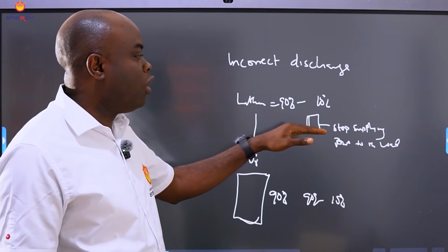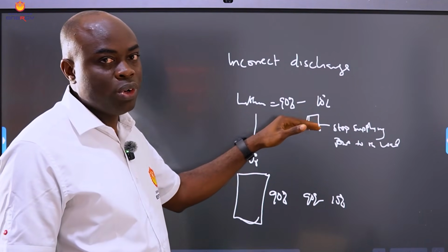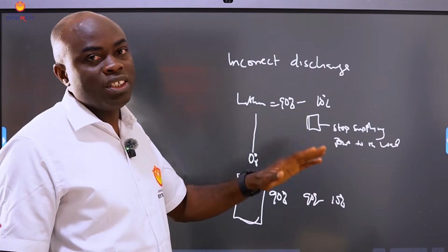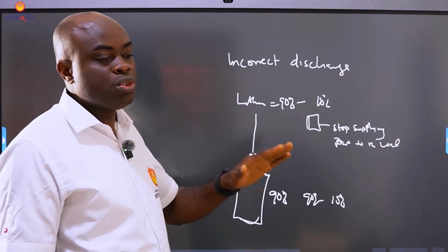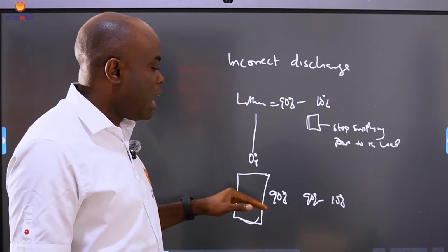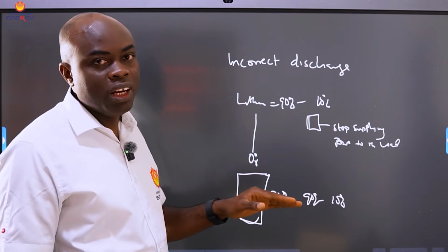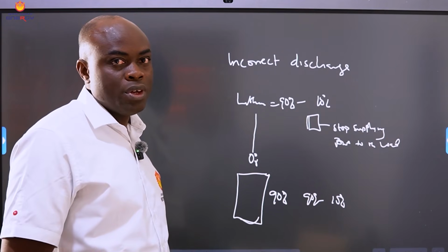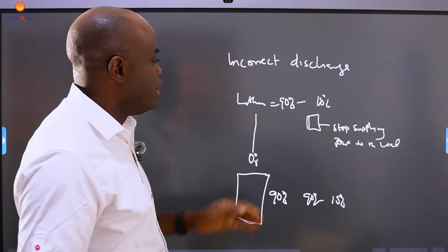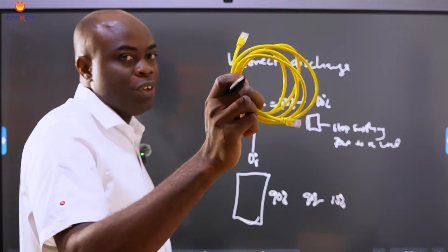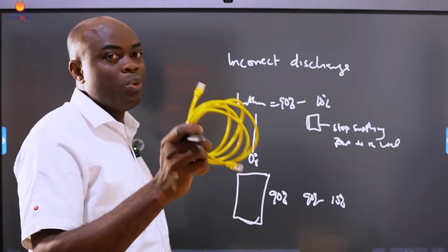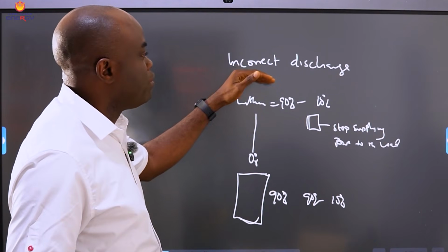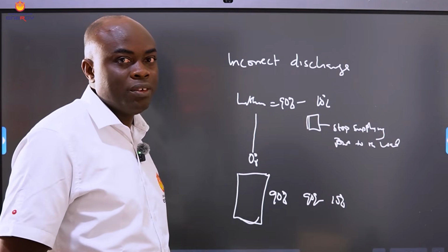But if it's one of these stand-alone inverters, or inverters that don't have communication between the battery and the inverter, it will discharge the battery down to 0, because there was no command telling it, "I've been discharged to my safe level, my recommended DOD, depth of discharge, stop discharging." So that's one of the benefits of having your BMS. It helps to regulate discharge. But if you don't have this communication cable, it discharges your battery to a bad level, right?